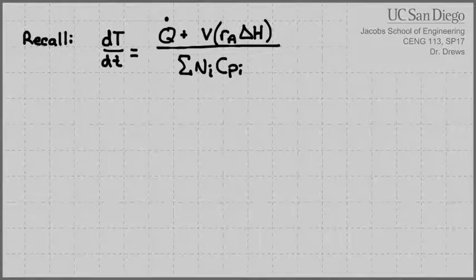If we had a ton of stuff in there, or that stuff had a very high heat capacity, that is, it took a large amount of energy to change its temperature even a little bit, then we wouldn't see a big change in temperature. That's one reason why we can occasionally add inerts to a system. They don't participate in any other term in that reaction, but they sit there as a sink for energy in the denominator.